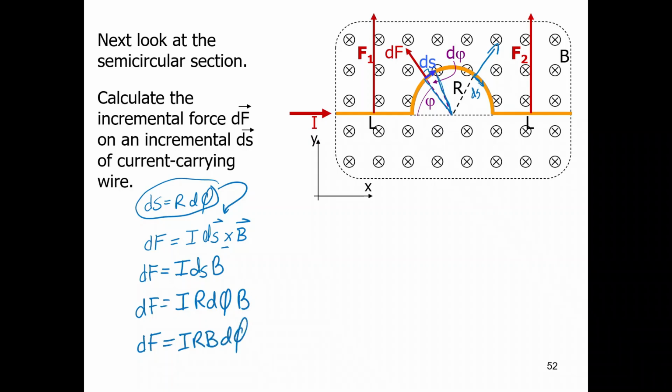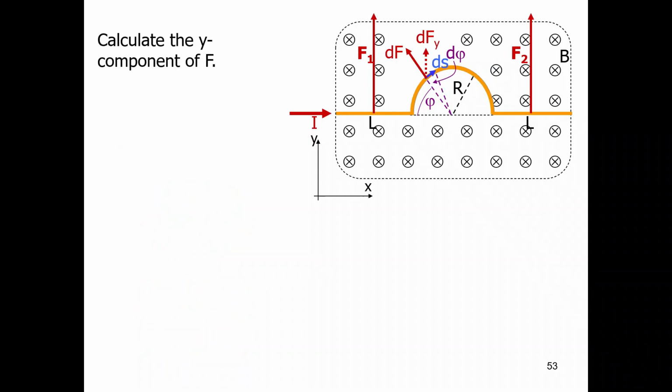Now the problem is that we have both X and Y components to deal with. So we can see that my force is going to have X and Y components for that little bit that we chose right there. If you were to break this into components, I know they show dFy right here, but I'm actually going to use this triangle over here where that's dFx, and then I have dFy right there. The reason I do that is because phi is right here, and because we're going to integrate in terms of phi, and phi is my angle right there that I'm starting at for this particular point, I'm going to use that.